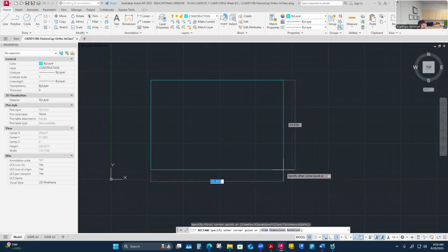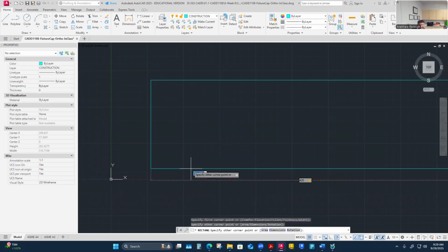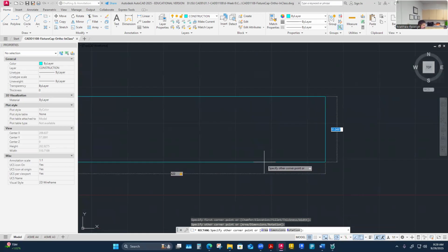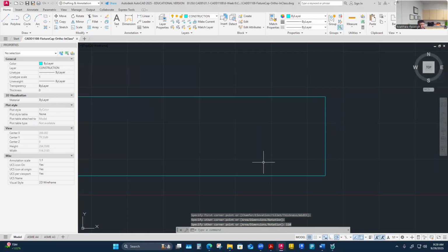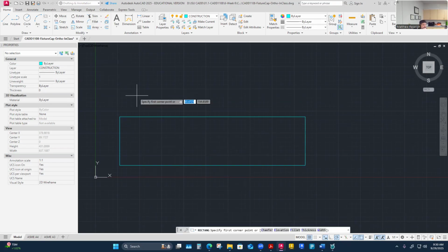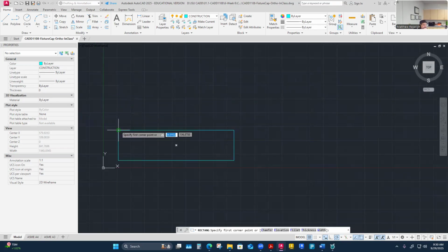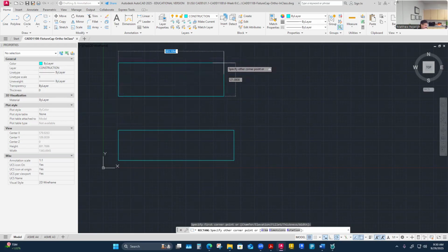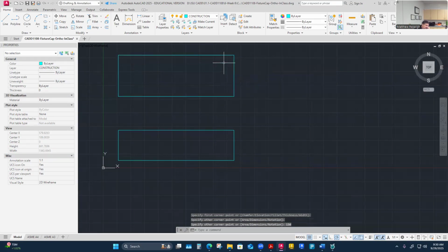What I need is 420 millimeters by 110 is what I decided. So it's just really long, not very tall part. And then I need a top view for that. Maybe I need it to be the same 420. And this one I decided is 150 millimeters because it was the 120 ear width depth plus the 15 on each side is 30 plus 120 is 150 is how I determined that.